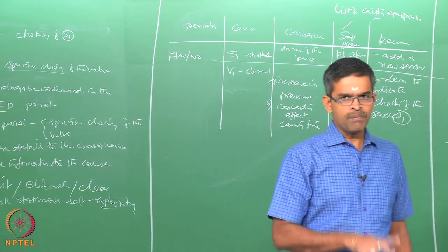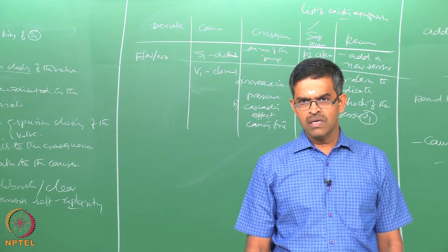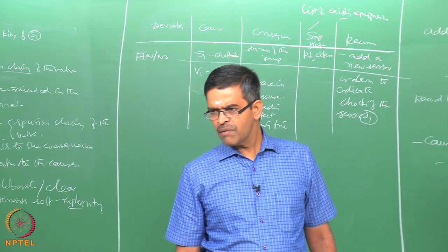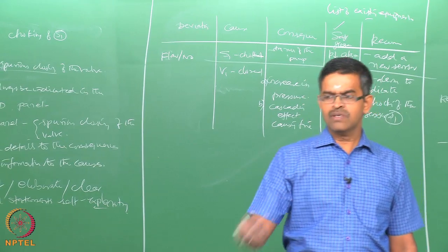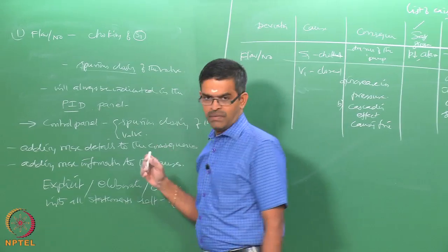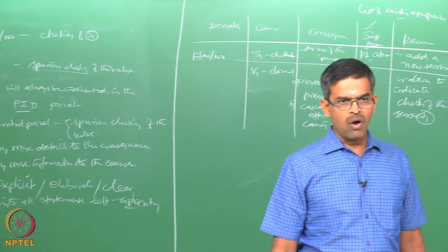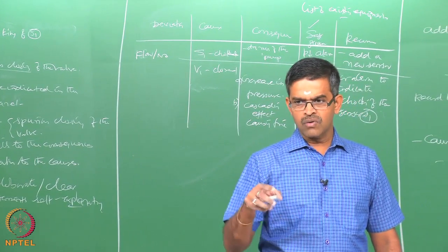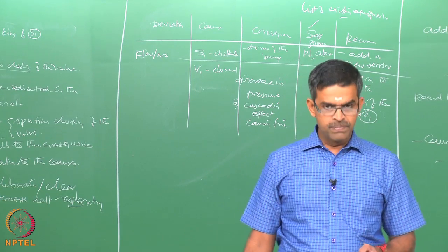Therefore, any existing protective devices which either prevent the cause or safeguard against the adverse consequences should be explicitly mentioned in the Hazop report. Safeguards need not be restricted only to adding equipment or hardware. They can also be extended to giving sufficient training to people, because if an alarm is activated on a spurious closure of a valve, somebody has to physically close the valve if it is not operational automatically. Therefore, intensive training given to the person on the control board is also important, and can be a recommendation in this particular example.